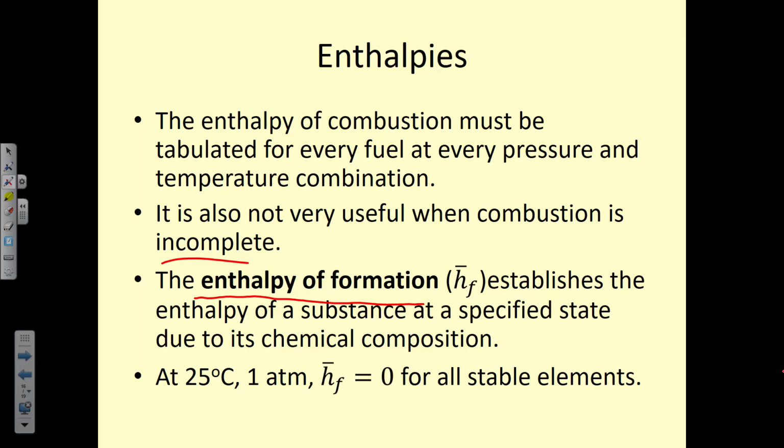Instead, we can look at the enthalpy of formation. It's almost like looking at it from an exergy point of view. It establishes the enthalpy of a substance based on its current chemical composition. So if we look at the enthalpy of the substance before the reaction and after the reaction, using those values we can calculate how much it changed during the combustion process, and from that determine how much energy was released.